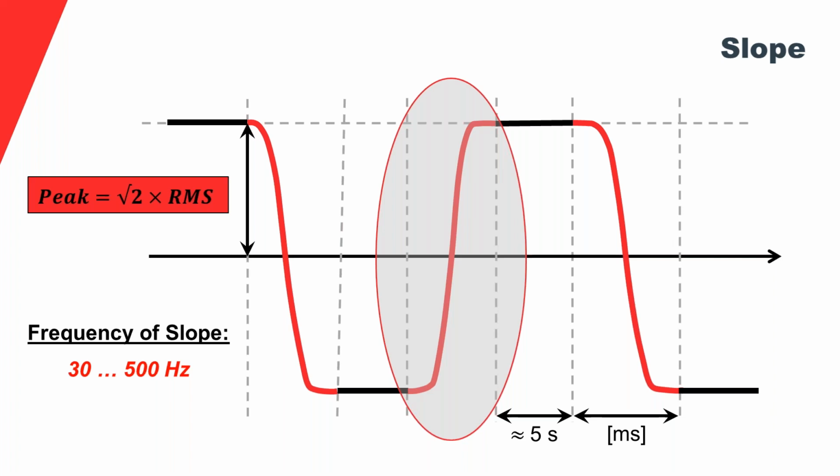Now, the inception of partial discharge: you want to do partial discharge testing and duplicate the same physics as 50 Hertz power frequency and damped AC. The inception voltage is also a function of the frequency, as was established and is well known for many years now, but it is a function of the peak voltages.